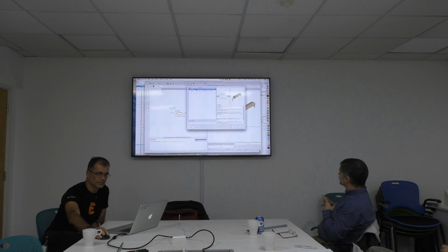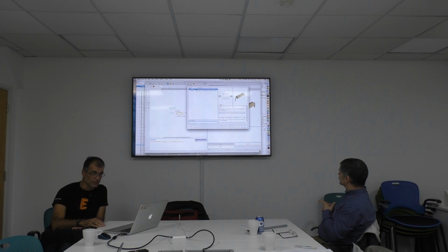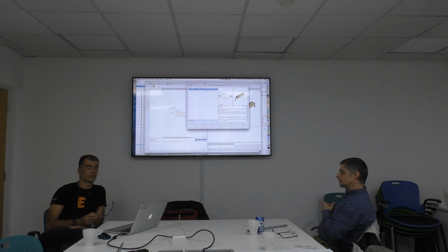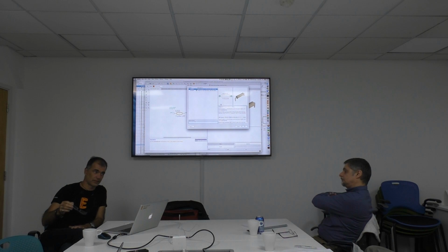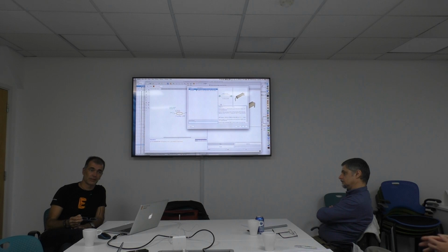Please look here. You can define a variant name. If it's only one variant, then it's not a problem. Think of our 555 from yesterday. It was available in the DIL case, through-hole mounted or a surface mounted device. Then I have to decide the variant names.